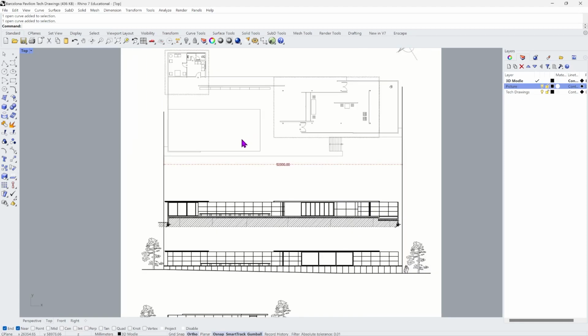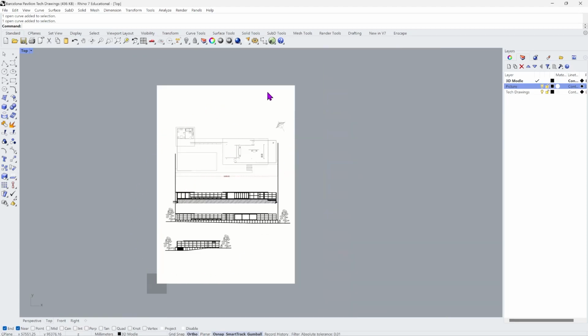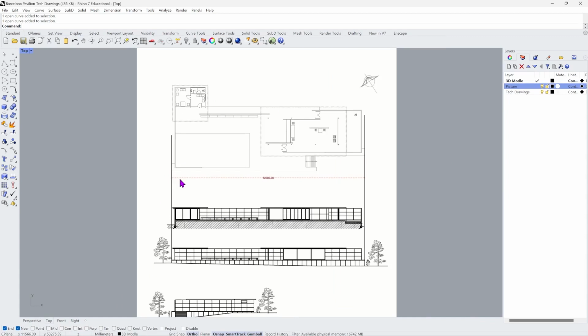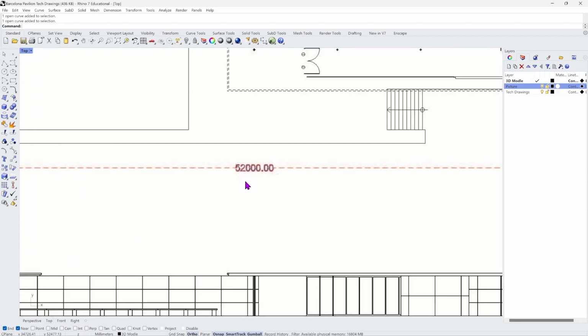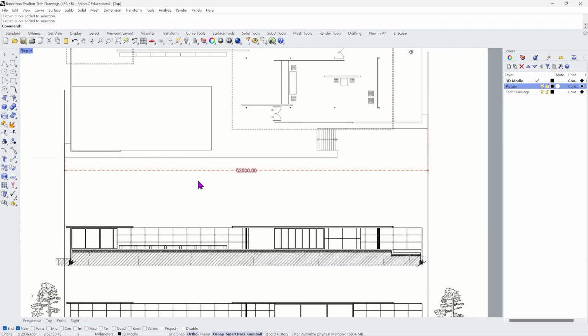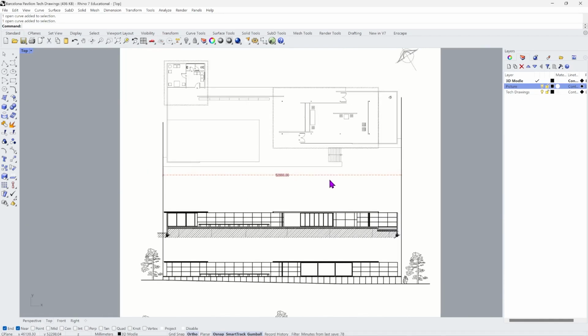And what we want to do, we want to scale this image and every single traced technical drawing in it. We want to scale it to 1-to-1 scale. The easiest way to scale in Rhino is either using a scale factor or using a reference of a specific measurement that you have already included in your image or in your technical drawing. So for example, in here we have a single measurement that specifies that from the furthest corner on the left to the furthest corner on the right, we're supposed to have a measurement of 52 meters across.